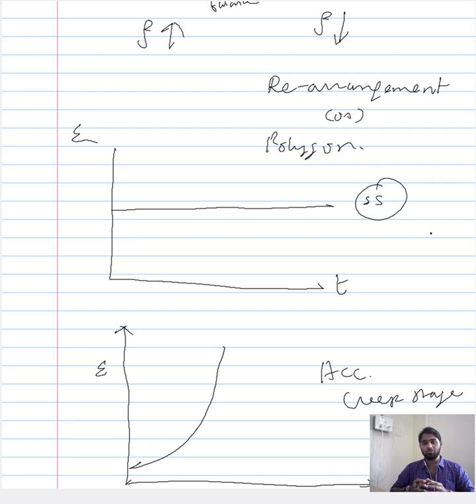So there is a decent balance between the condition introduced by the stress and the condition introduced by the high temperature, the latter favoring plastic deformation. While the stress condition impedes plastic deformation, the high temperature condition favors it, so you have a balance in the steady state creep region. However, as the time increases, the effect of the temperature, that is the favoring of plastic deformation, gets more pronounced towards the end, and because of the exceeding amount of plastic deformation, your material ultimately fails, and that is what you observe in the accelerating creep stage, or the tertiary creep stage.